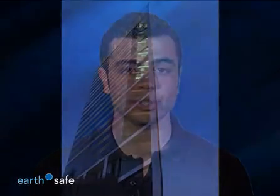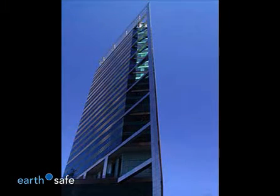User needs, such as the building loads and the expected runtime during emergencies, will determine the size of the fuel system. The site location will determine the fuel storage location. For example, a high-rise building in a downtown urban area will require fuel storage inside the building.